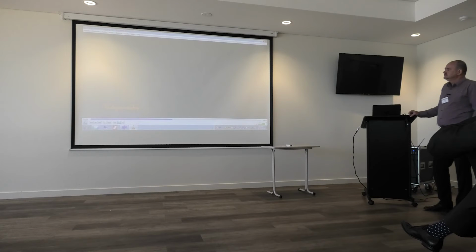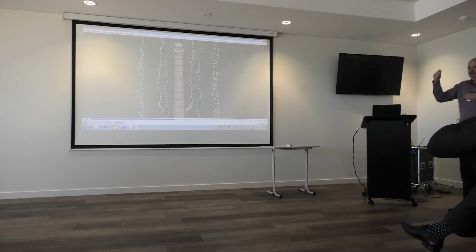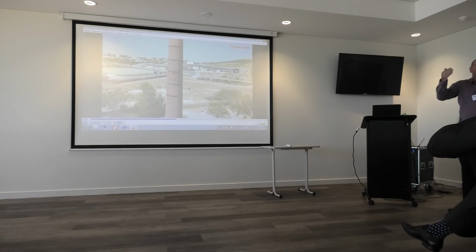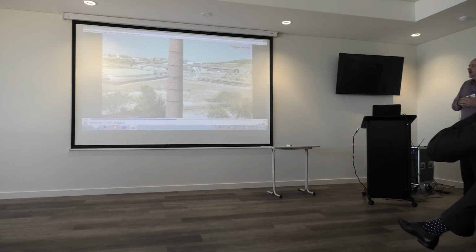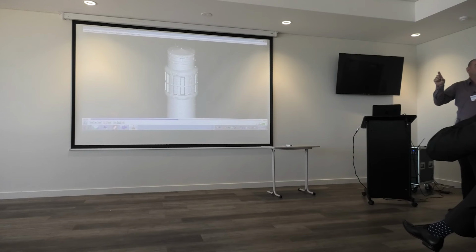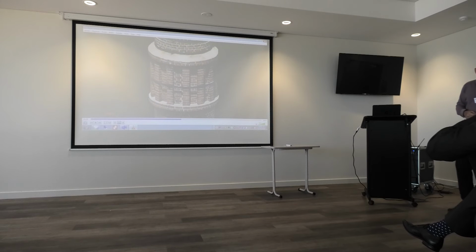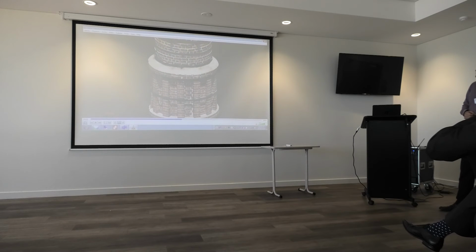Photogrammetry. A good photogrammetry model involves the capture of a large number of photographs. The principle of photogrammetry is you're taking photos with a lot of overlap over a subject matter, and once you get those photos back, we process them through software that positions where those original camera points were through triangulation, and determines the depth to where the actual structure is. That model has been recreated from the photogrammetry space.